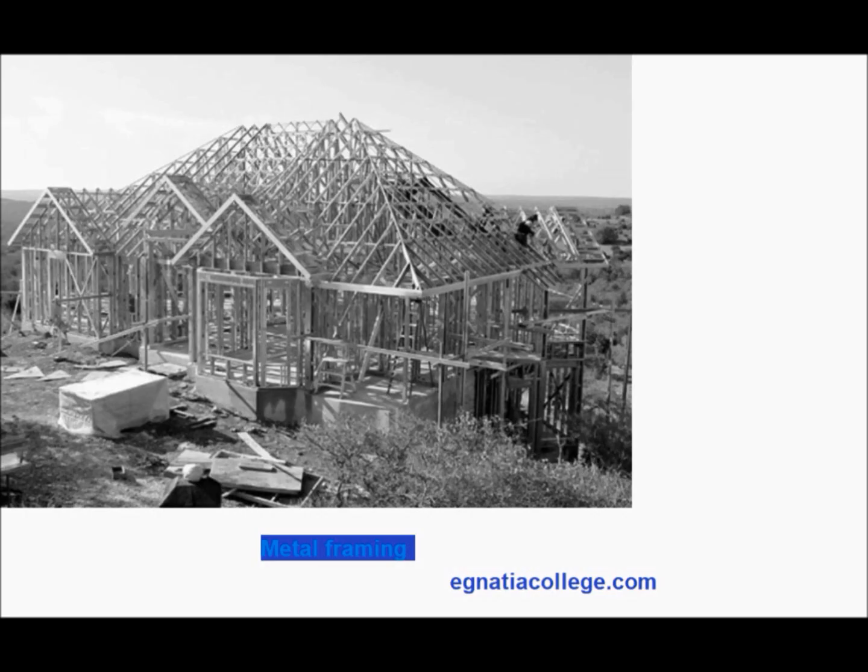Unlike wood framing, steel framing uses tracks and runners in place of bottom plates and top plates. The lighter, less expensive grades of metal framing are not as strong as wood, so they are used primarily for interior partitions in conjunction with other structural materials. Metal framing can be pre-assembled just as you would pre-assemble wood framing.